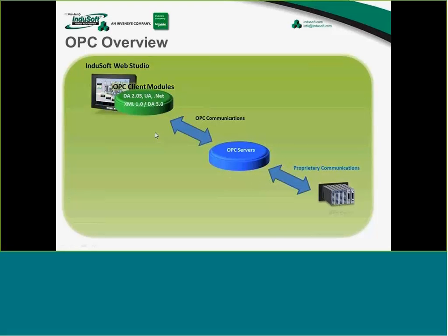And if you look at it in this circumstance, the OPC server is kind of like a translator, where maybe we speak English to the translator, and then the translator would speak another language on the other side. In this case, we're speaking OPC to the server, and it's speaking the proprietary communications, whatever protocol that PLC supports. We don't necessarily need to know what it is on that other side, nor do we care. Of course we care, but the communications that happen on the other side are kind of transparent to us. We only speak OPC to the server, and it handles the communications on the other side. Much like if you were speaking to a translator and you only spoke English, he or she would speak English or French or German or Portuguese on the other side. So that's kind of the idea of what OPC is. And as you'll see in Bob's presentation, it really can be much, much more than that. I'm trying to oversimplify it to make sure that everybody gets the concept and the idea.